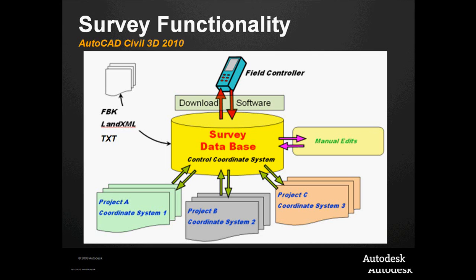They'll think they're alignments, because that's typically what a LandXML sees. So there's a different flavor of that called survey, like survey grade LandXML, that will understand the difference between a center line and a curve. Basically, when the line work comes in, we want it to be a survey figure and not converted into roadway alignments or something like that. But yes, I don't have a good example of that, but we can talk about that later.